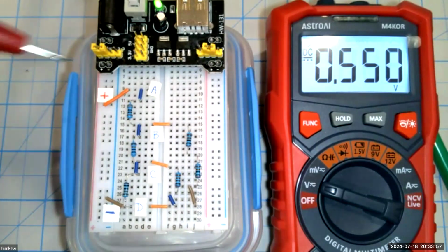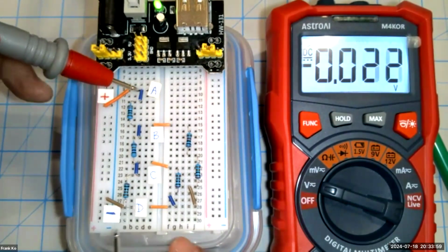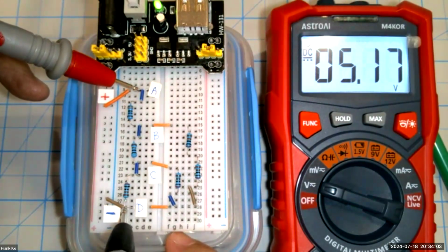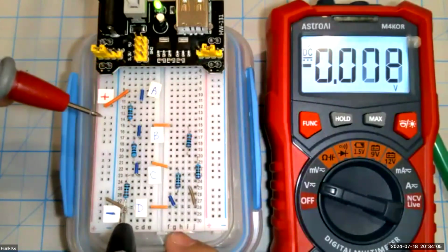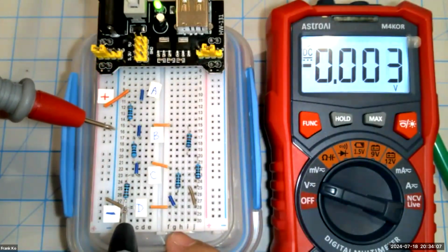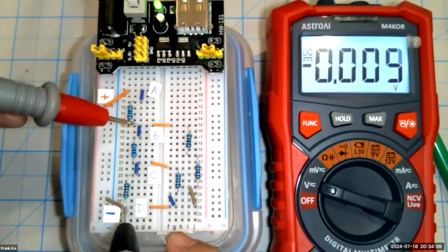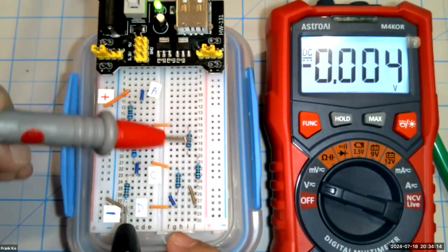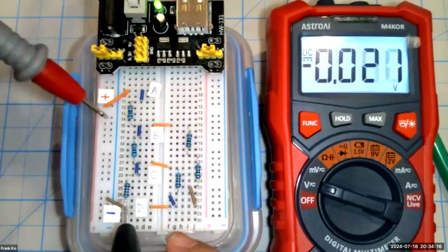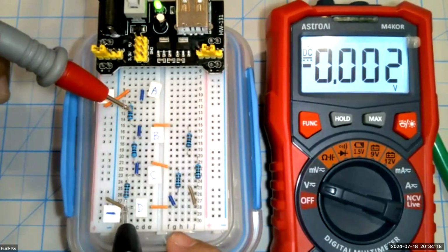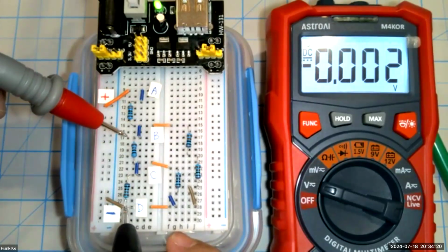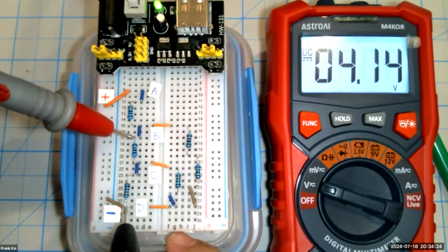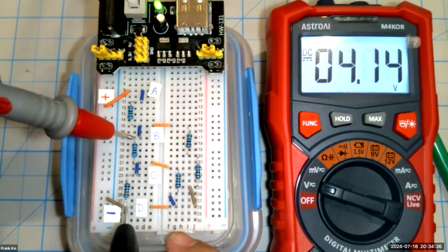So first of all, I'm going to double check my source voltage. We have an excess of 5 volts. I'm going to double check my voltage at point B. So with the original values, that changed from 4 to 3.2 something because we added these load resistances. Let's see if I have, with the new resistances here, am I able to achieve something close to 4 volts at point B? Look at that, 4.14, pretty close.